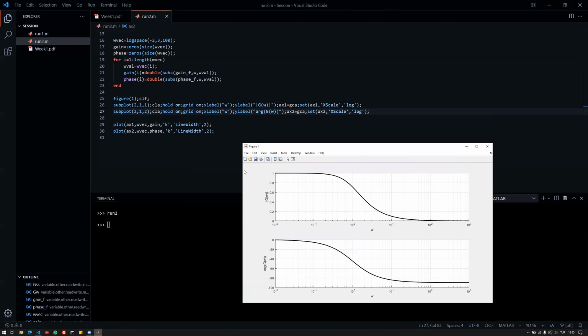But the bode function from the control system toolbox has just one difference, that being the y-axis values here. If we use 20 log |j omega|, then we will get decibels, but here it's not decibels. That's the only difference that is left. But other than that, I can see that the low frequency region has high gain value, almost equal to 1 or equal to 1. This means that signals applied with these frequencies will pass through without loss of any gain.